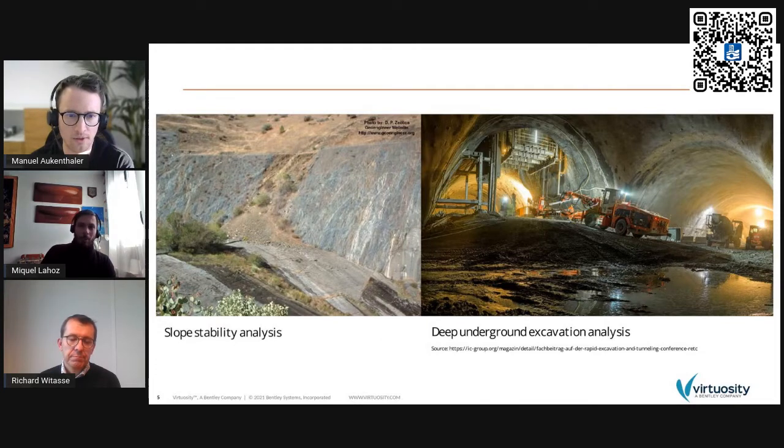I would say challenge number one is uncertainty. It's true that uncertainty is a factor in every field of engineering, even more in geotechnical, but even more in rock engineering projects. It's not that we need to manage uncertainty, we're navigating on it. So, a good start is always the geological history of the site. This will give us an idea of what to expect from what we have there, whether there have been major tectonic events and in what preferential directions, whether the stresses from those have been released or not, and also the probable composition of the rocks that we'll find.